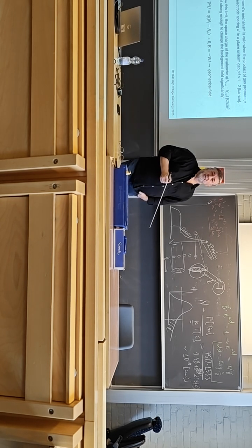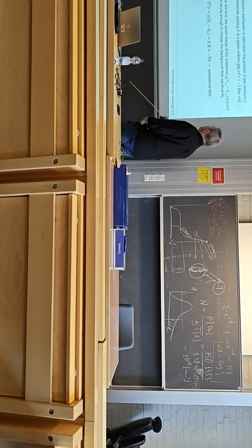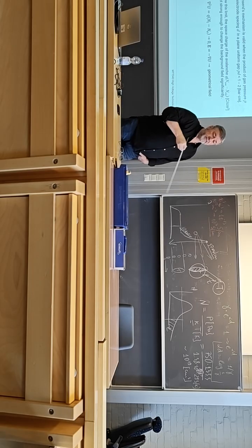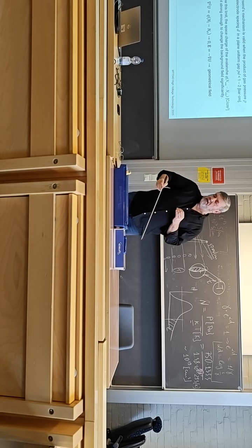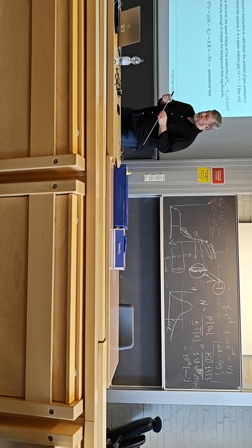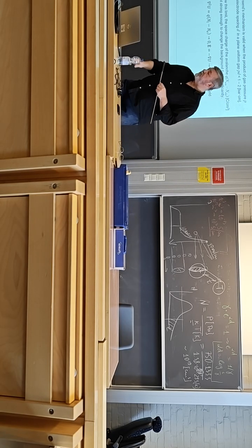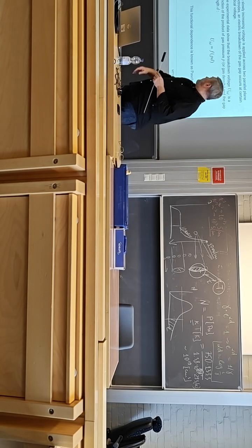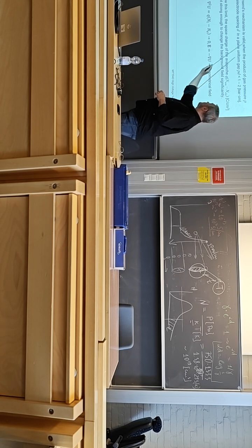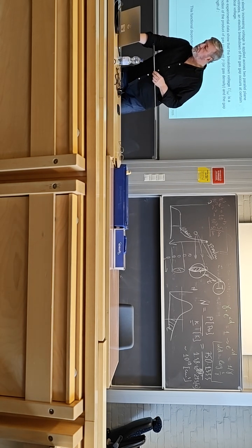There is no impact of this discharge on the electric field. But if this becomes high enough, then the transformation of electron avalanche type of discharge to another type, to streamer discharge, happens. For now, we will focus mainly on the Townsend type of breakdown. The streamer mechanism will come later.